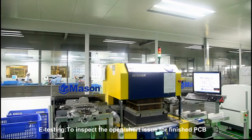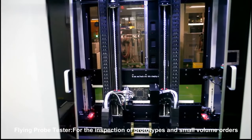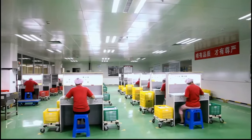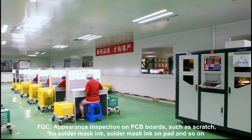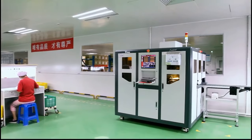E-testing, to inspect the open short issue for finished PCB. Flying probe tester, for the inspection of prototypes and small volume orders. FQC, appearance inspection on PCB boards such as scratch, no solder mask ink on pad, and so on.